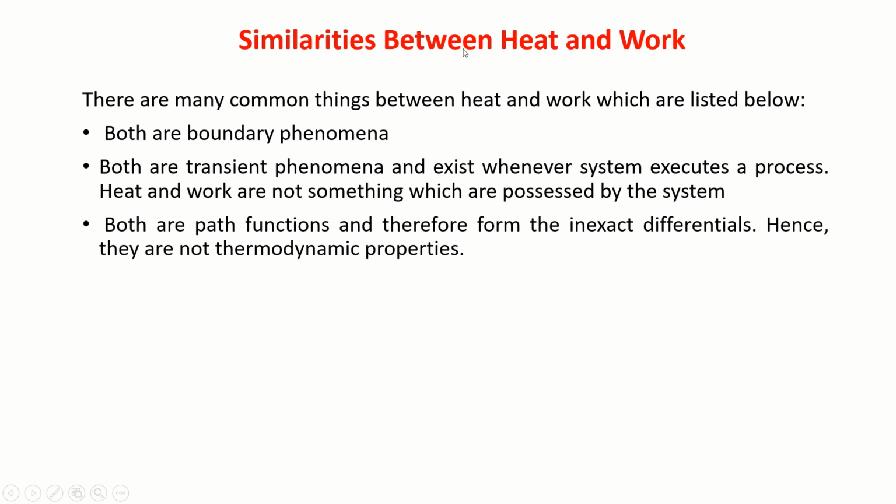So what are the similarities between heat and work? As I mentioned, both are boundary phenomena. Neither work nor heat are properties of the system. Both are transient phenomena and exist whenever the system executes a process. Heat and work are not something which are possessed by the system, hence they are not properties of the system. Both are path functions and therefore form inexact differentials. Hence they are not thermodynamic properties.